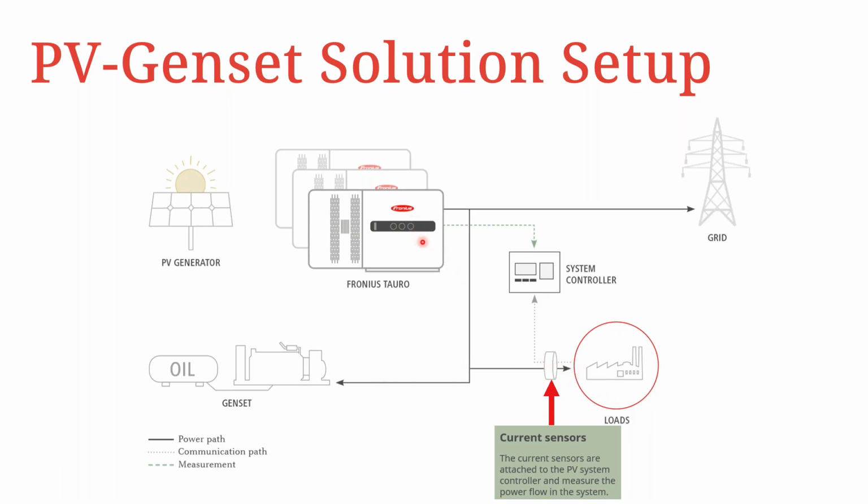Of course, as you've noticed, this is absolutely dependent on what is being generated from the PV. If this is 60, then it will throttle this one up to 40. If it is 50, this will be 50. Just as long as there's a good combination to provide for the entire load demand, basically.